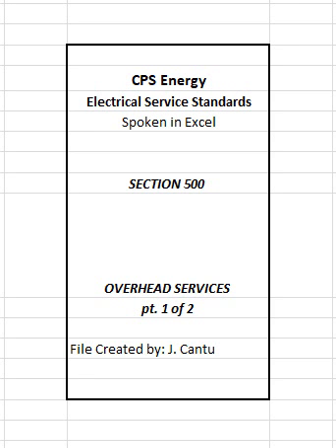3. Anchorage must be designed to withstand 750 pounds of load tension induced from the weight of the service drop conductors. Open, moused, service drops will require an anchor for each conductor. Cabled, bundled, service drops will require only one anchor. Customer must consult with the CPS Energy customer service representative to determine the type of service drop required, refer to Figures 506 and 507.